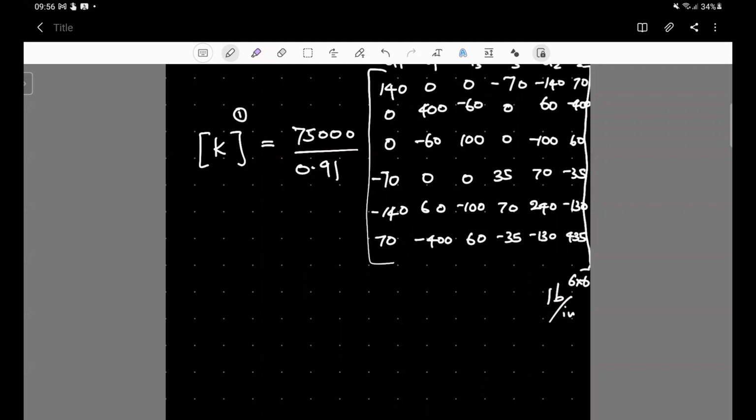It's already a 6 by 6 matrix, and if we use higher order elements and more degrees of freedom, let's say in the later sections, a linear strain triangular element, where the strain within the element is not constant, like in the constant strain triangular element,